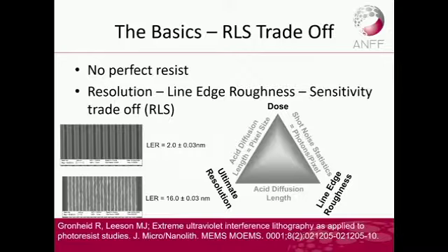And so to make the perfect polymer blend, actually the perfect doesn't exist. So you have to sacrifice something. Usually they work around an area where either resolution is important or roughness is important. But in the industry, they mostly care about the sensitivity as well because they want to be able to push, these days, 200 wafers per hour for the lithography process. If you do this in a clean room, probably you can have 1 wafer per day, 2 wafers per day. That's OK. But in industry, they will be producing 200 of these per hour. So they need very, very highly sensitive resist.